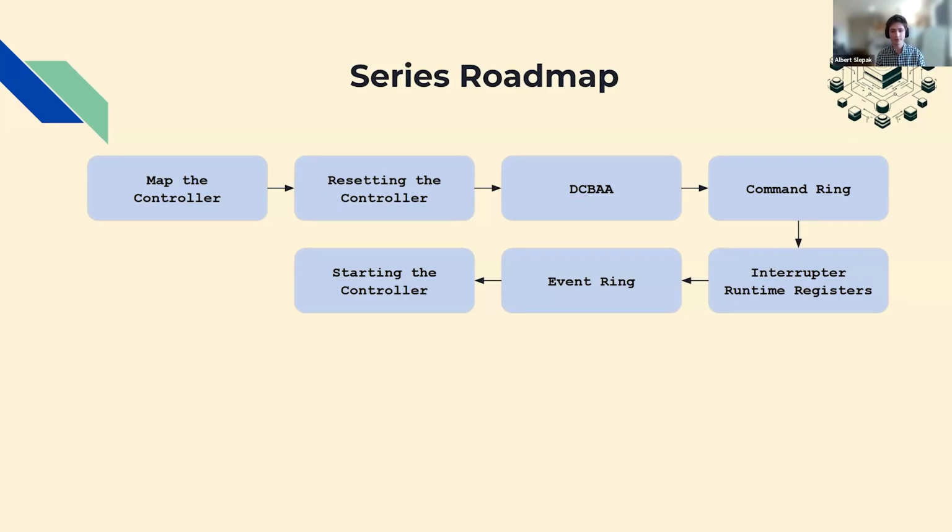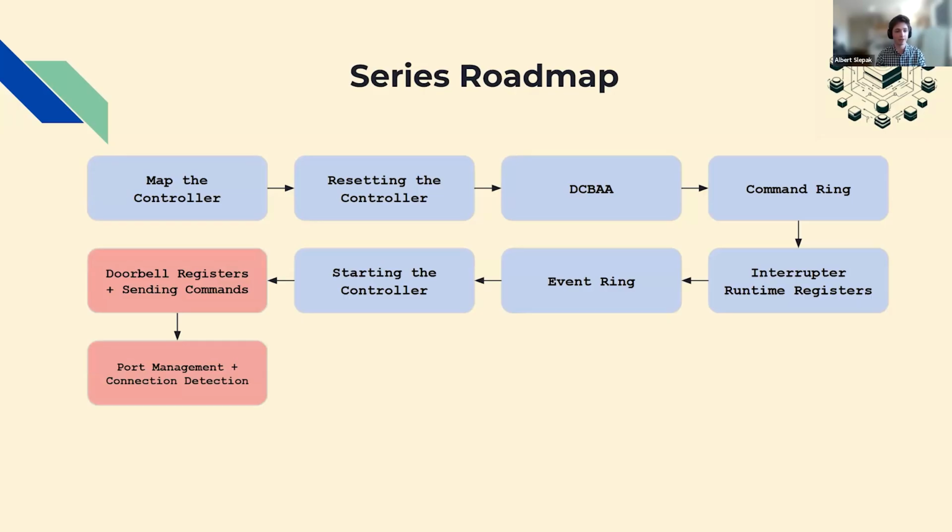After all of that is done, the tutorials will cover how to start the controller properly. And if no errors have occurred during these steps, then the focus will be on anything in regards to runtime. This will be the next phase or stage of the series. It will focus on actually communicating with the controller and sending it commands using doorbell registers, which are actually pretty cool. They're kind of like doorbells that you can ring. And just like a person opening a door and talking to you, the controller will respond, look at the command that you sent it, and provide you with a response object.